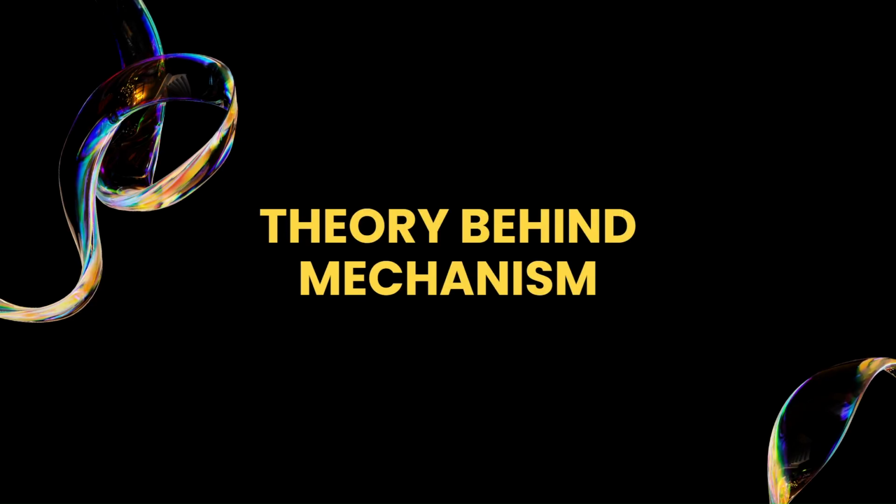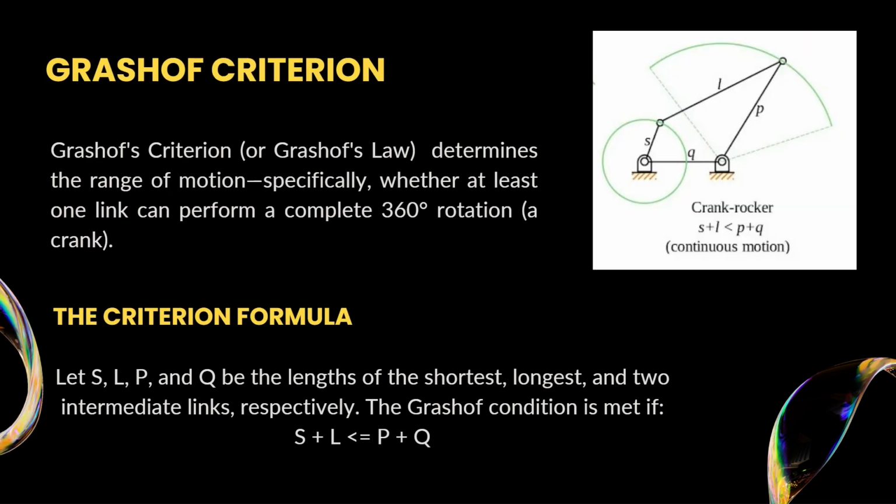So let's start with the theory behind our mechanism. At first, let's talk about the Grashof criterion. This criterion determines the range of motion. That is, at least one link in the whole mechanism can perform the complete 360-degree rotation. For the mechanism shown, we have a 4-bar mechanism. We have 4 bars, out of which the smallest one will have the length of S and the largest one will have the length L. The other two bars have the lengths P and Q respectively.